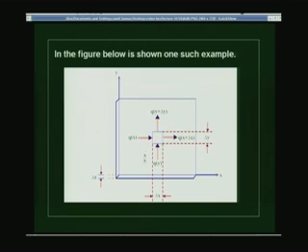So that is the amount of heat per unit area per unit time which is flowing out in this region in this direction, and Qx is the amount of heat which is flowing out in this region, in this direction, per unit area per unit time. So then you take a small section like this, and you say that whatever is coming in should go out at steady state, because the temperature here is not changing. Okay, so whatever heat comes in should go out, and we have insulated the top and bottom of the slab, so the flow is only in the xy plane. So that simplifies our analysis here.